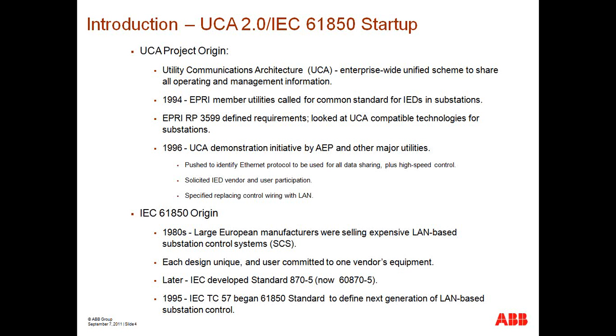Okay. One of the interesting initiatives from this specification was perhaps the need of utilizing the communications network to replace control wiring. This is something that's important to take into consideration when we talk about GOOSE messages, and we will see, as we look at some of the settings or parameters that need to be taken into consideration for a GOOSE message, how that comes into play.